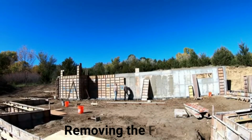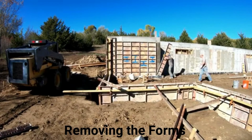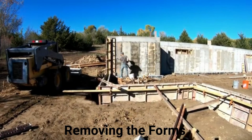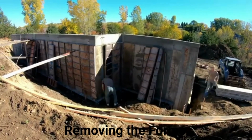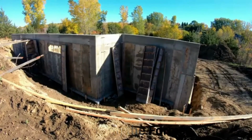Removing the forms. The process of removing the forms from around the concrete is called stripping the forms. The workman must not strip the forms until the concrete has properly set. In some cases, the concrete is allowed to cure before the forms are removed. Concrete which has set but has not cured is called green concrete. It is firm but not hard and strong.